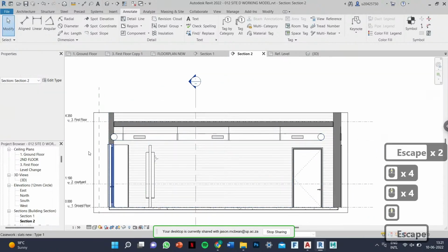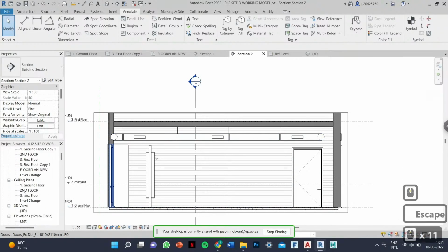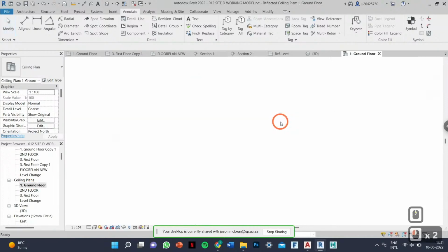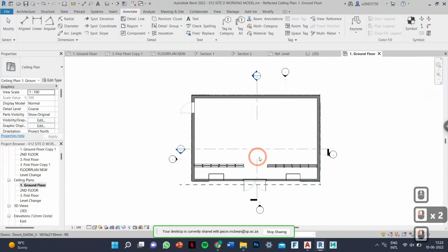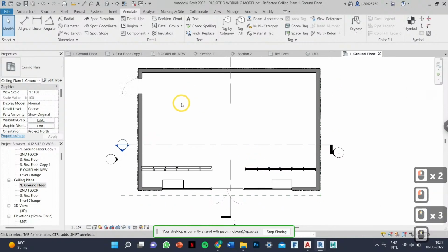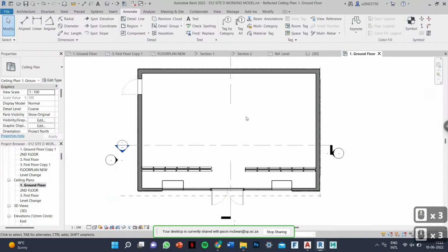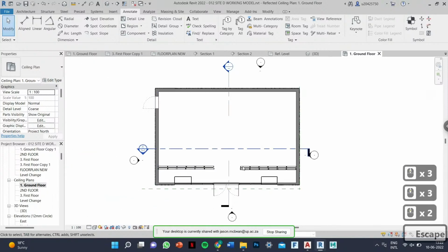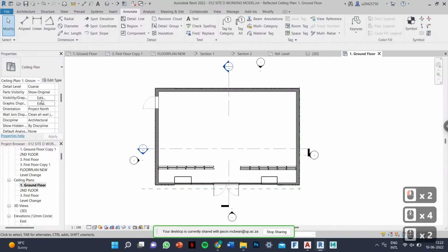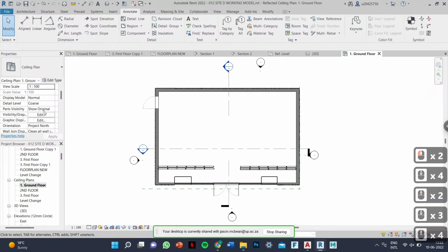Now, let me just help you with your ceiling plans, which should be this ground floor one. If you look up at your ceiling plans here, you draft in the ceiling. So again, annotate. Depending on how the ceiling is going to work, you can literally draft what it's going to look like if you can't model it. Say now I want a 600 by 600 ceiling grid. I might just have to set this higher. So let's say ground floor ceiling plan. Let's just change this. There is a video on how to use this, okay?